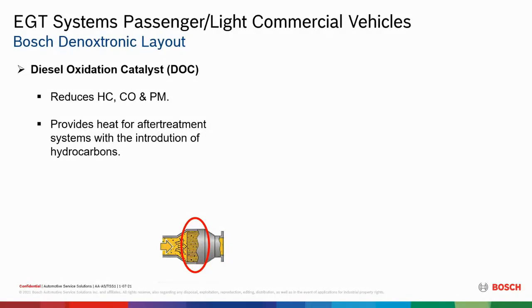Oils can contaminate it, the wrong types of oil that are put into these diesel engines, because there's always some blow-by past the rings. There's nothing you can do about it. It's what it is. And as a matter of fact, it's even worse with the light duty passenger vehicles, because the service intervals are a little bit more frequent in those, due to the fact that they know this after-treatment, when it's being induced into the engine, does wash down the oil. So we're getting fuel in the oil as it is. That adds more blow-by and more fuel to go by there with the oil as well. So contamination of that happens.